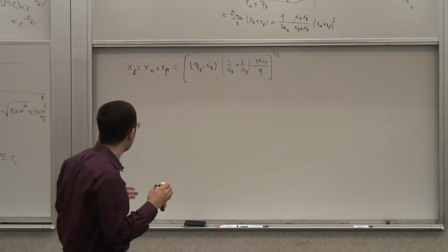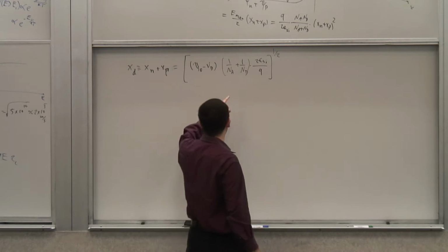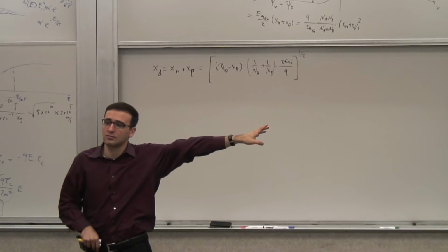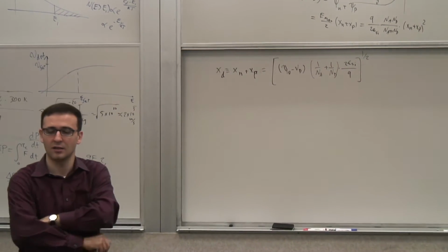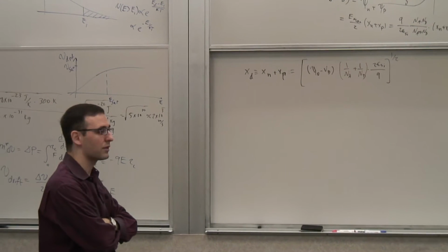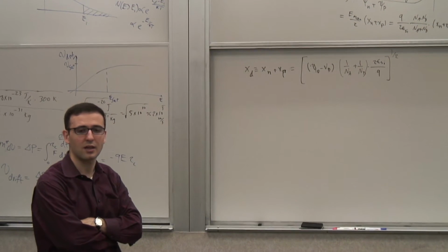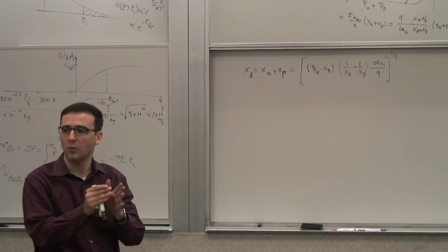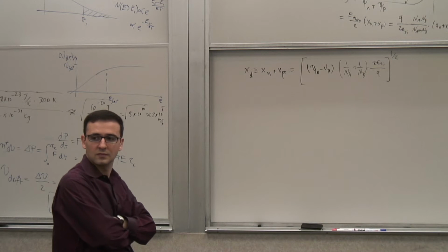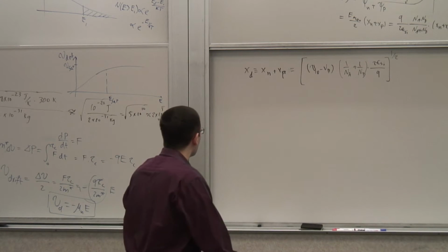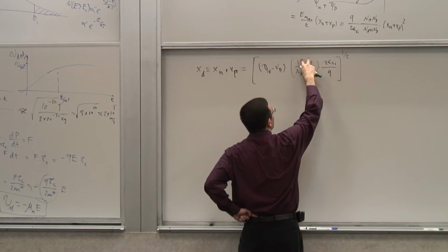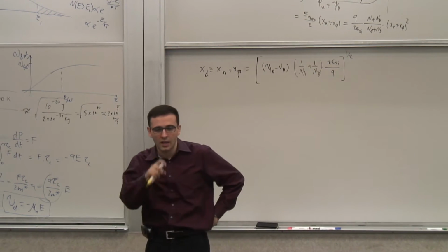So let's say, for the sake of argument, that Na is much greater than Nd. So you have a lot higher doping on the P side than the N side. Which side will carry most of the depletion width? Which side is the side that most of the depletion region falls into? Lightly doped side. The lightly doped side, right? Because the smaller one of these two, because they are in the denominator, will give you a larger term in the summation. And it also makes sense.